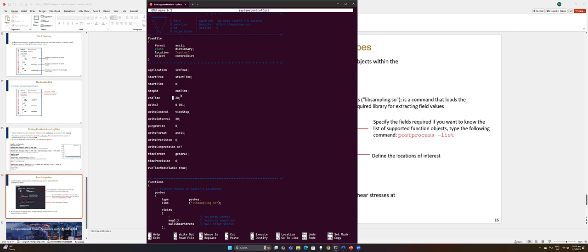Let's make it 10. But one thing I want you to take care of when you are running these cases is that you shouldn't run your simulations shorter than what you expect. Let's say you have a 20-meter long pipe and your velocity is 0.1 meters per second. You can calculate the duration it will take to obtain the solution.